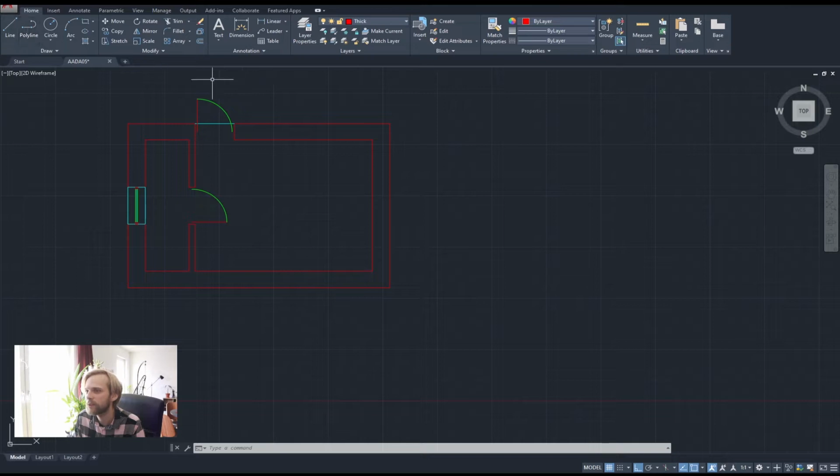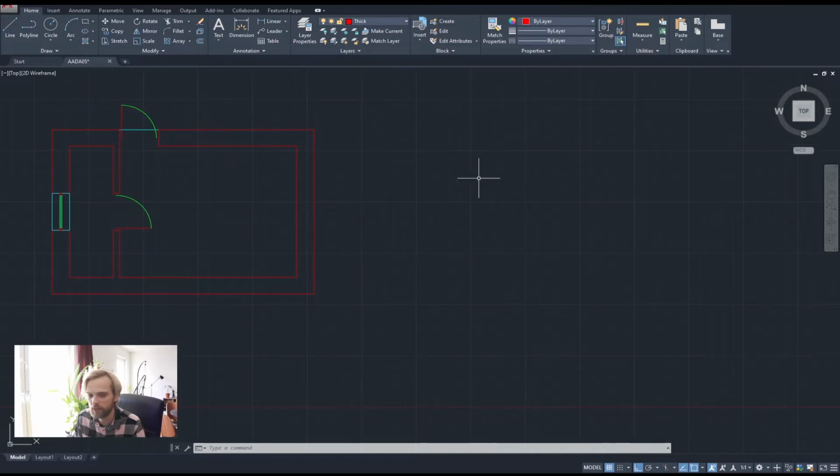So let me just create, just to see the proportion of the room, let me just somewhere else on the screen, let me just create a size of a bed that I want, and it's going to just be, I'm drawing it with Polyline, 2,100 millimeters long.